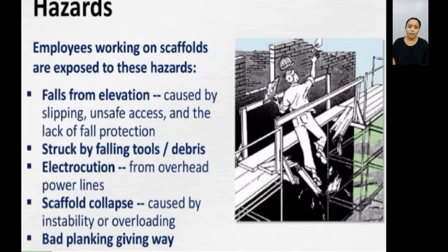The answer to that question is that the standard prohibits work on a platform cluttered with debris. Next is electrocution from overhead power lines. Next is scaffold collapse caused by instability or overloading.